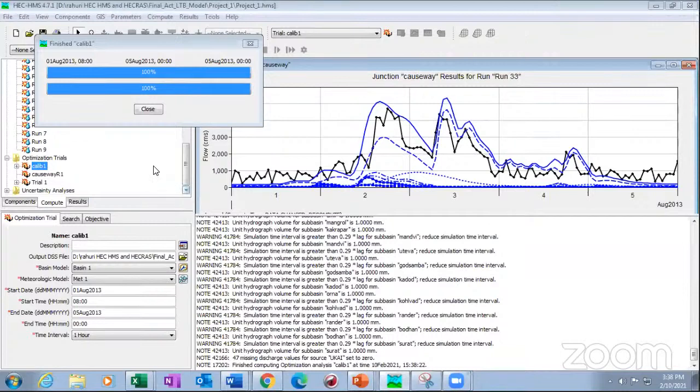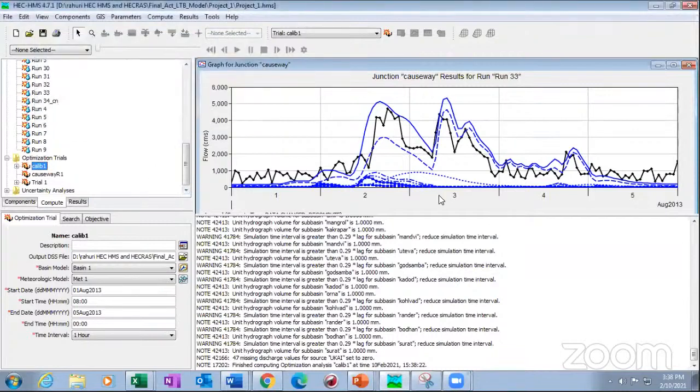Calibration. So this is how you do the calibration in HEC-HMS. It's a very simple model, but if you want to do simulations of different varieties, or carry out some different research, you can. Even in the 2020s, 2021, many papers are still getting published using HEC-HMS. Though SWAT is a very good model, it requires a lot of parameters. With fewer parameters, if you want to study some effect or some impacts, you can use HEC-HMS. So it is a simple yet effective model you can simulate.